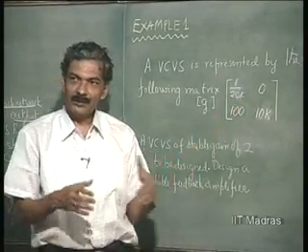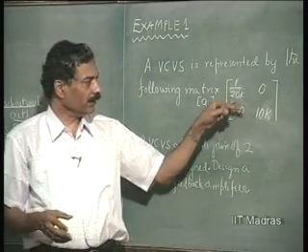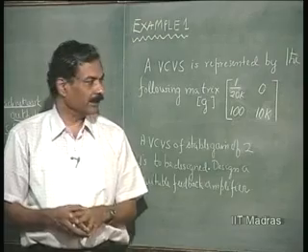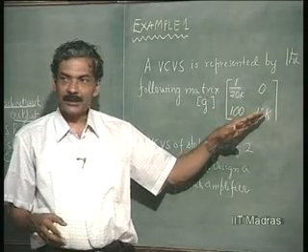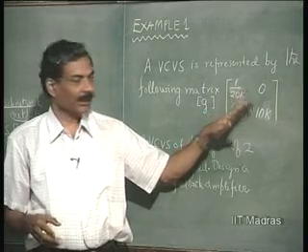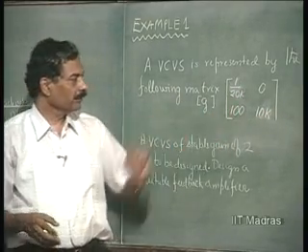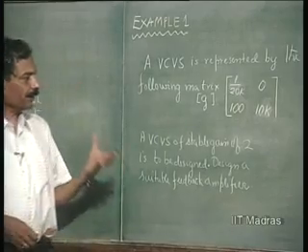This is representative of a single stage, and of course for a single stage the gain will be negative. So, if you couple it onto another stage with another inversion, you will get a gain of 100 very easily. So, two stage amplifiers cascaded, okay, with input impedance of 20 k and output impedance of 10 k. So, this is a practical situation.